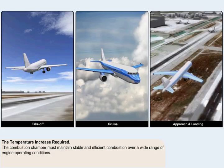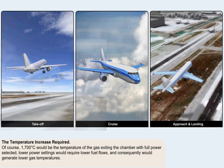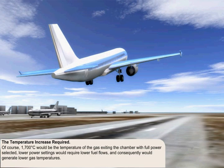It must also be remembered that the combustion chamber has to be capable of maintaining stable and efficient combustion over a wide range of engine operating conditions. Of course, 1700 degrees Celsius would be the temperature of the gas exiting the chamber with full power selected. Lower power settings would require lower fuel flows, and consequently would generate lower gas temperatures.